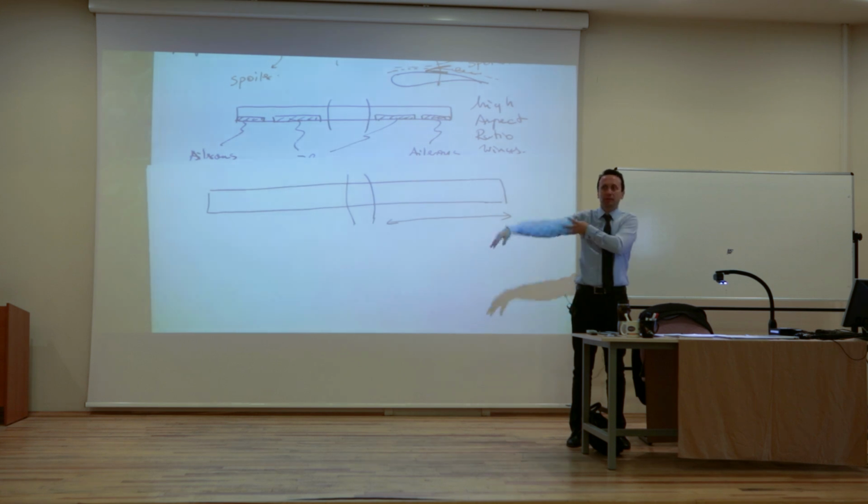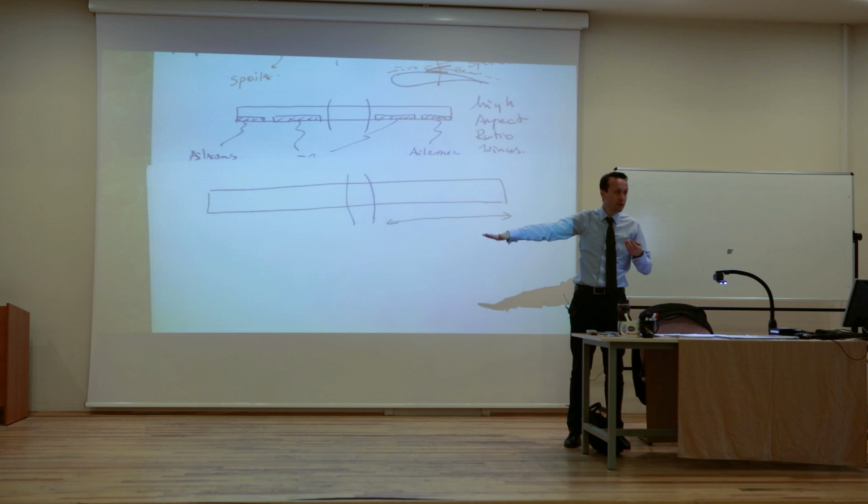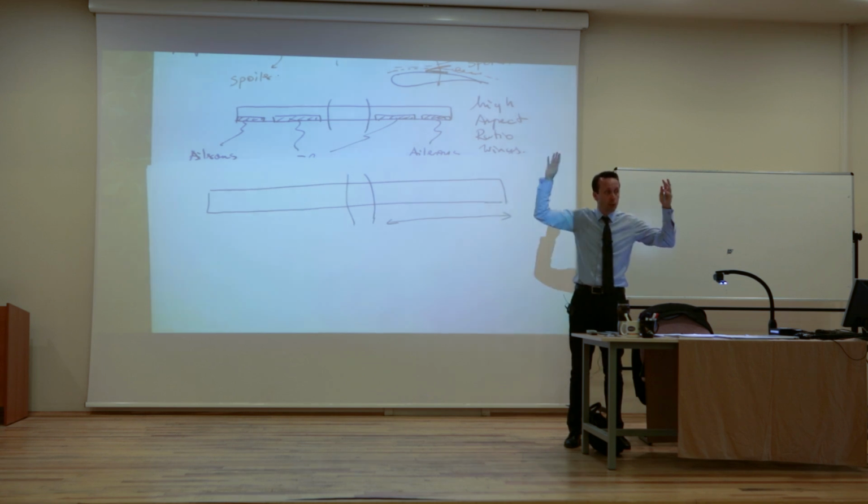And the interaction between the structure and the aerodynamics can be quite dangerous at times. This movement we call flutter. Okay? So it's an aeroelastic problem. It's the structure plus the aerodynamics that interact together that could potentially, not always, potentially cause this to resonate. If it's in resonance, then you can actually break your wing. Because that oscillation can increase, and it can break your wing.